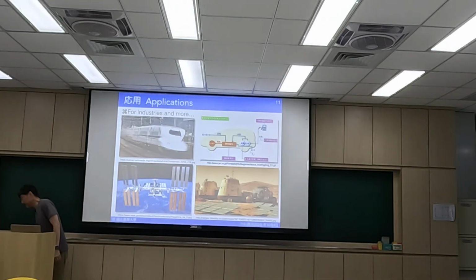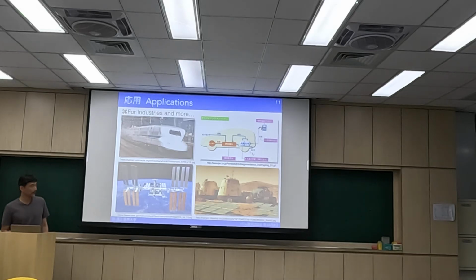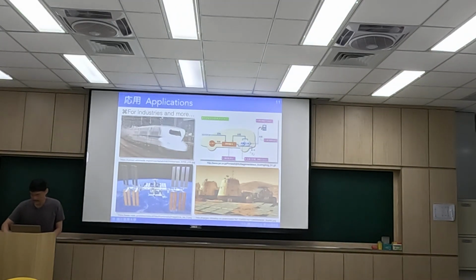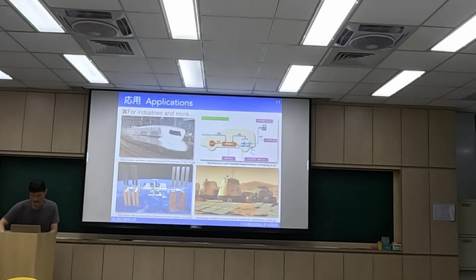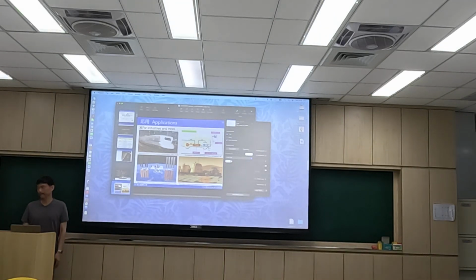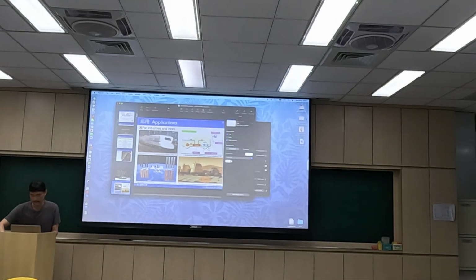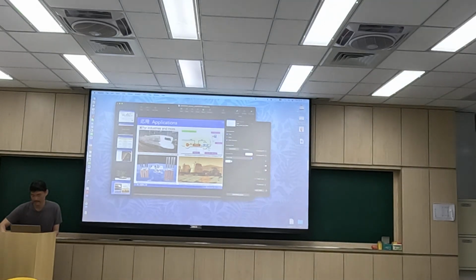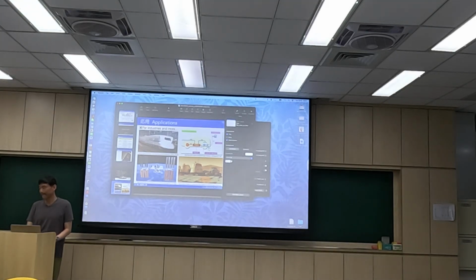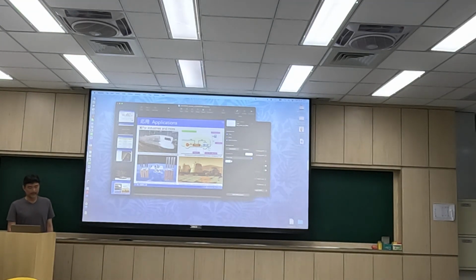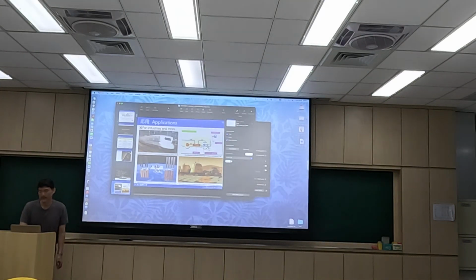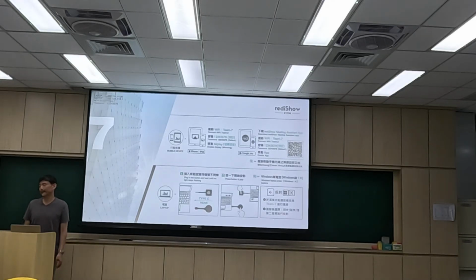Thank you, Professor Ueno. Since he's visiting during August, unfortunately we cannot touch on boiling just before that, but you guys should have an idea: when there's a film building up on the heat surface, the gas is more insulating than the water, so the heat cannot propagate directly through the bubble. Then the heat will accumulate on the surface and damage the electronic device on the surface. So how to get rid of the film, or increase the heat flux Q, is what current scientists are working on.